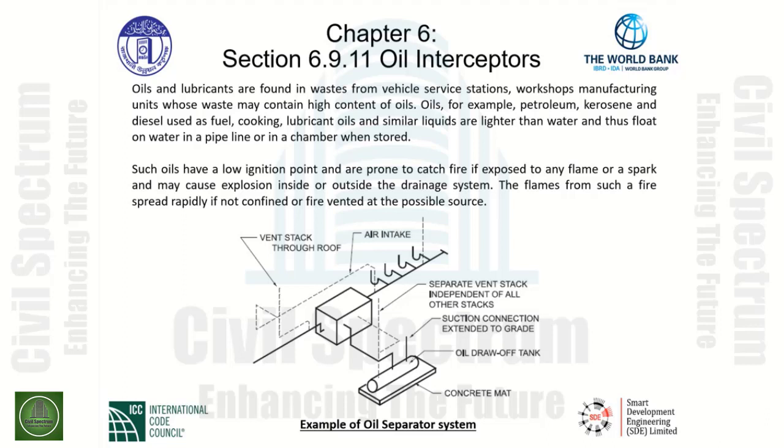As you will note, we have a lower outlet indicated on the oil separator. This is where clean water can discharge to the sanitary drainage system. As well, we have venting indicated according to the manufacturer of the oil separator, and we are venting any type of ignition, fumes, things of that nature completely to the outside of the building.